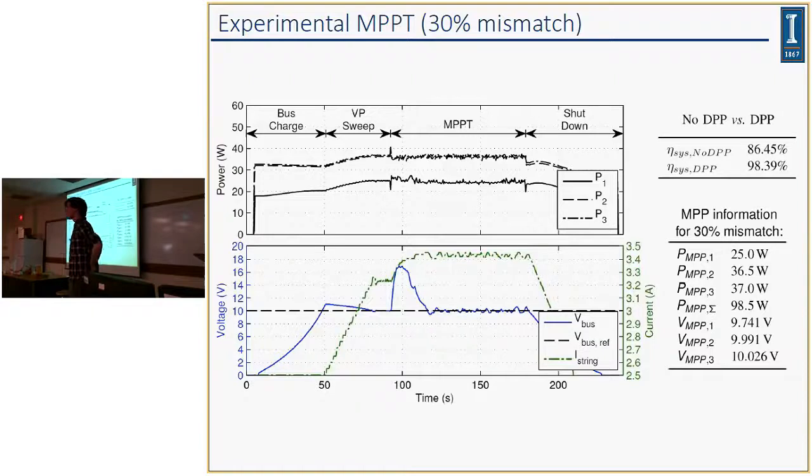So you couldn't put this in a system that's already installed without communication from the system. Yeah, that's another downfall. So I think there are really 2 drawbacks for this topology: you need 2 differential wires, and you need communication between the bus voltage and the central inverter. If you maybe retrofit an extra device to do the measurement, you don't need to change the control of the central inverter, you just need information.